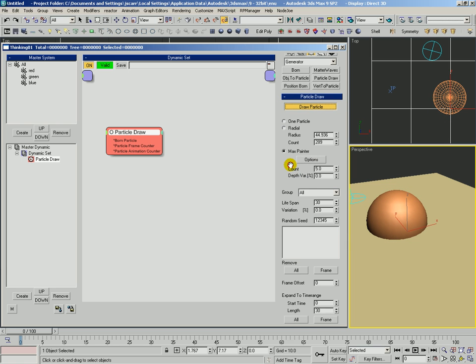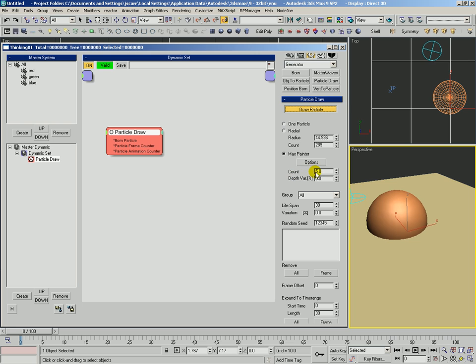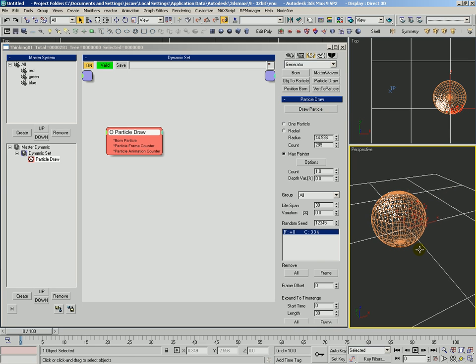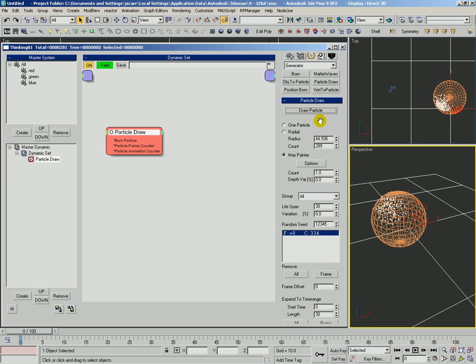And then some other parameters that we should look at are the count. So this is going to define how many particles per second, or pressure. If we reduce that to 1, it's going to bore much fewer particles. You can't really see that too well. Let's go ahead and draw on the plane.